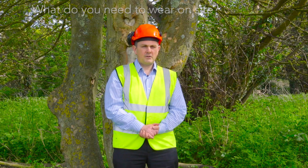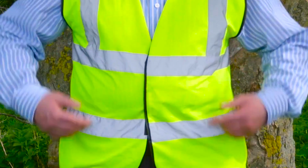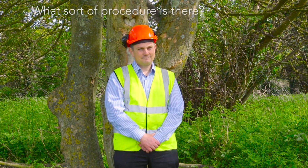There's certain elements of health and safety kit that you'd have to wear on a live site. These consist of some sturdy boots with steel toe caps, a high visibility vest so that you can be seen by other site users and particularly people operating plant, a hard hat so that you're protected from falling debris from other site workers, and possibly ear defenders and some eye protection depending on the specific site conditions, but you'd be instructed on that by the site manager.